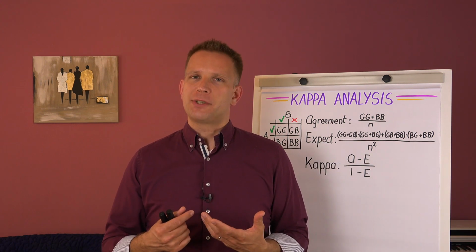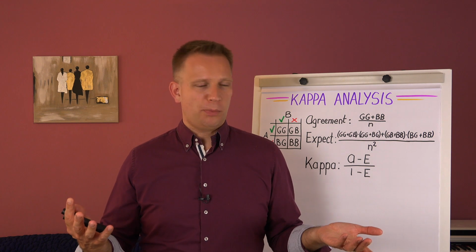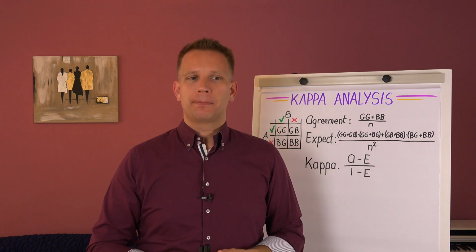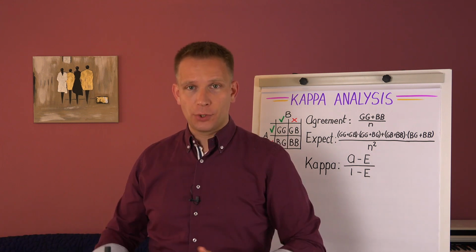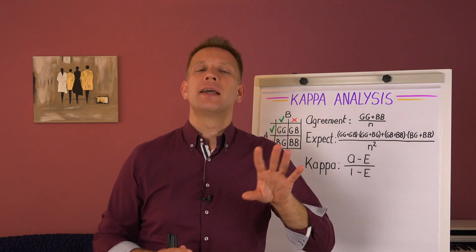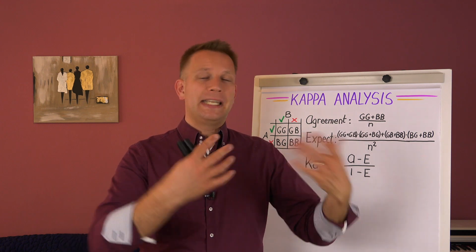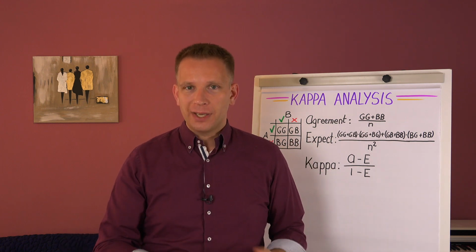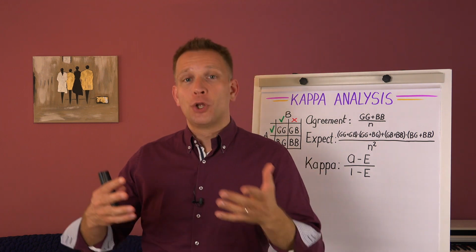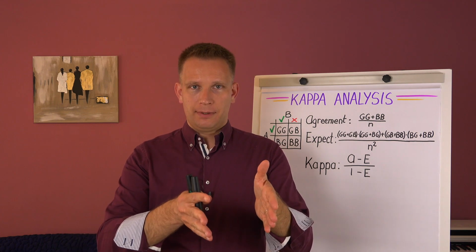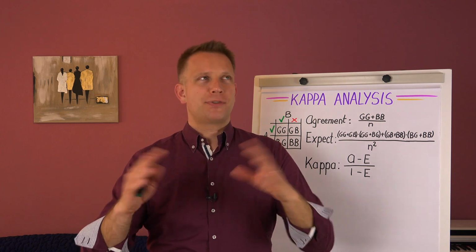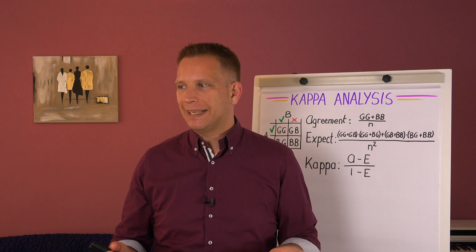And also for this type of measurement, you want to know, if I've got two operators, two quality control people, and I give them the same product, will they both say it's good or both say it's bad? So how stable is the measurement system itself? This is not really about the product. It's not about the defect percentage I have in my production. It is about, do my testing operators, my QC people, agree on the same products being good, the same products being bad? Now, pass-fail is the most commonly used thing here.